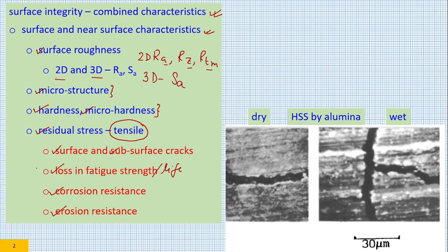What is the implication of these in mechanical design or mechanical systems engineering? If there is a product, say a power transmission shaft, and you can see both subsurface and surface cracks, then definitely you are not going to use that shaft in your machinery. How do you reveal subsurface and surface cracks? For subsurface, you may have to go for ultrasonic evaluation or X-ray evaluation, and surface cracks can be revealed by a dye penetration test very easily.